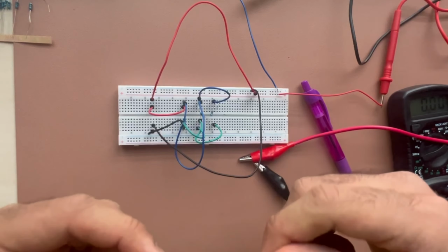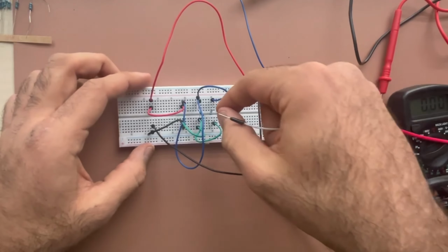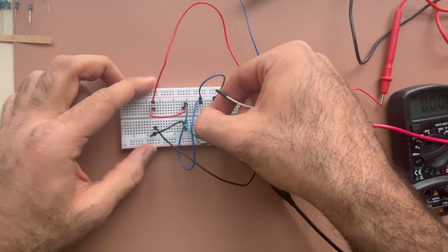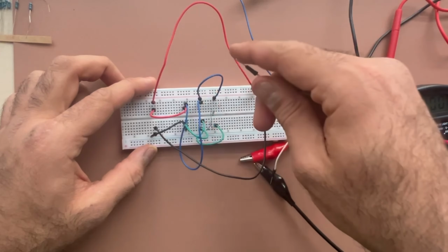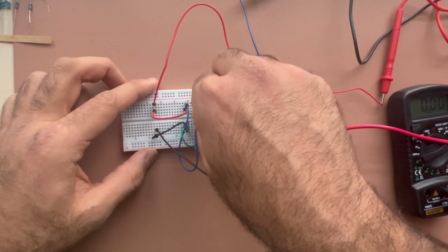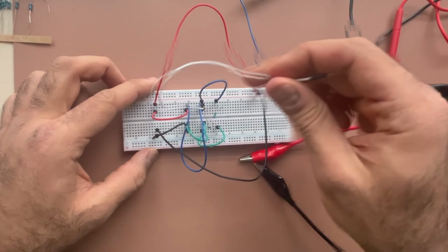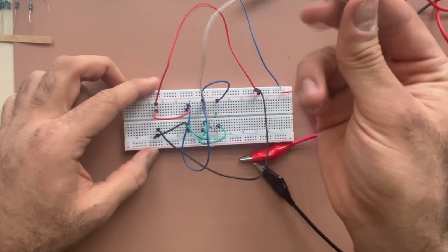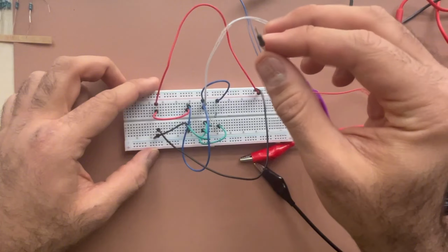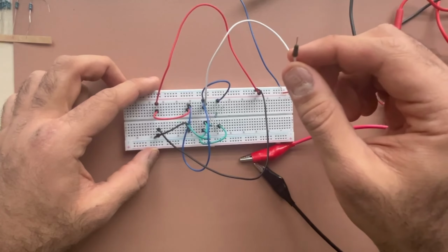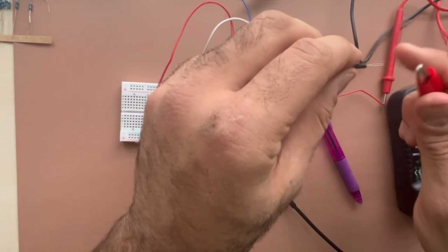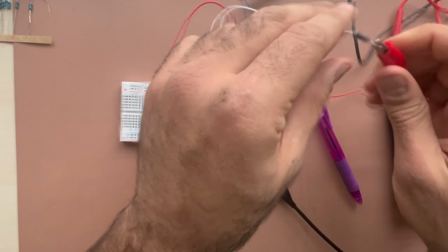At this point, I'm going to use the third jumper and I'm going to disconnect, for instance, this guy, right? If I do that and use the jumper between, it means that instead of just disconnecting any of these two and having an effect over the whole system, I'm going to get another spot in between while both of these guys are connected to each other, and then I'm going to measure the current. At this point, the final answer should be right. Let's see what would happen.